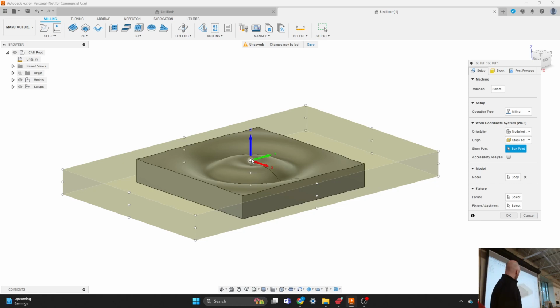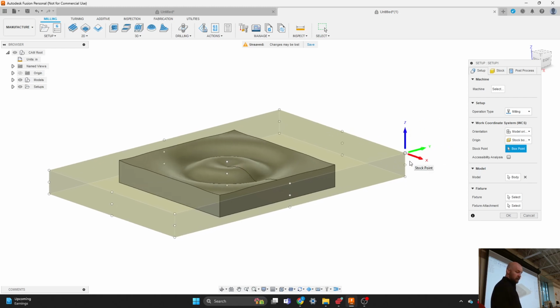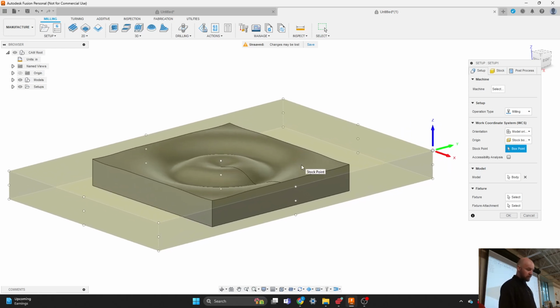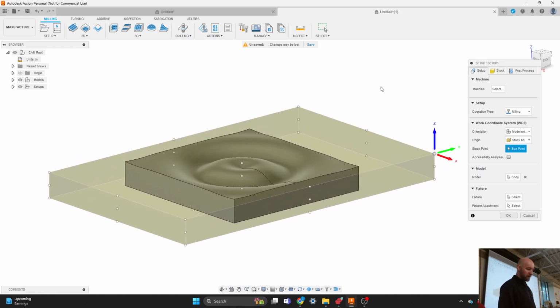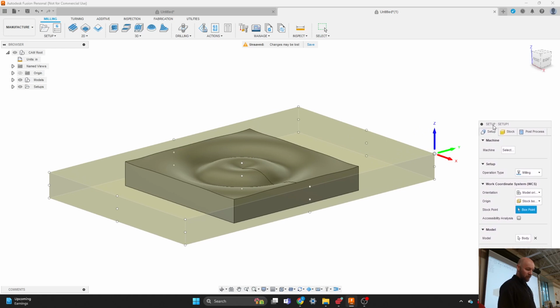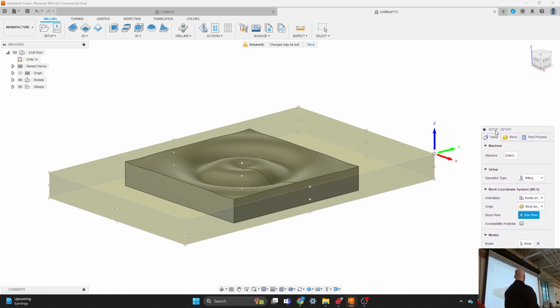But if you want to be real precise about your origin, I would set your origin over on one of the corners. And I'd pick a top corner. So the way we set our origin is if we click on our origin here, and when we click on our origin, you'll see all these little white dots around the outside of our piece of stock here. I always set my origin the same way. If I do something the same way every time, I'm not gonna be confused about what past me did when I actually go to cut this out.